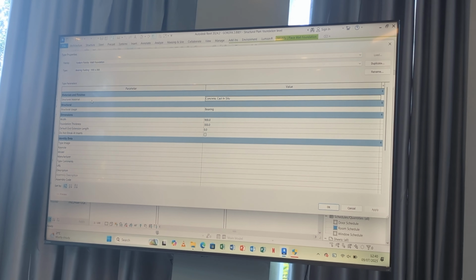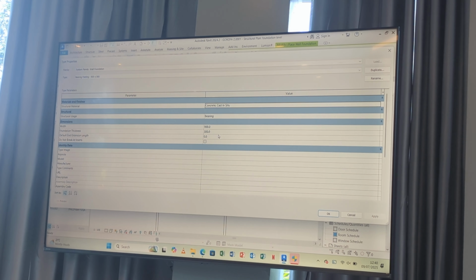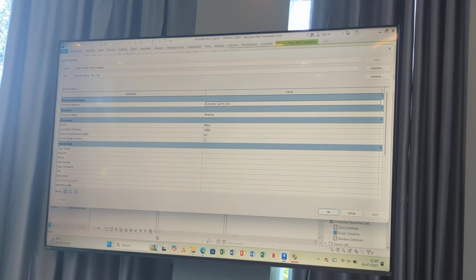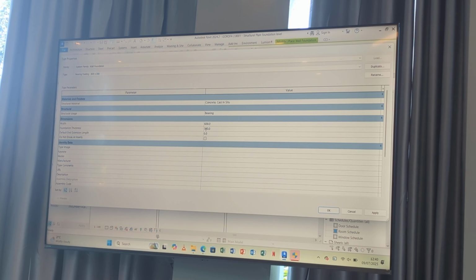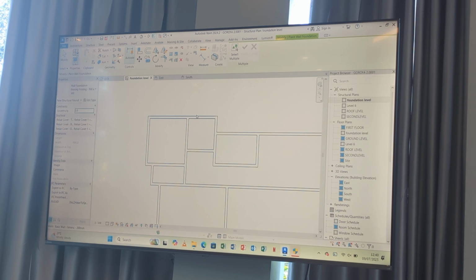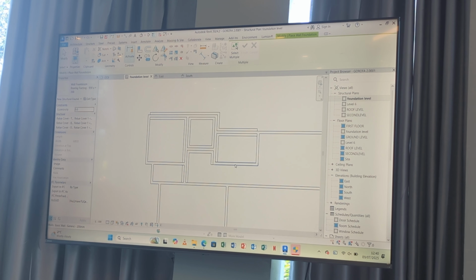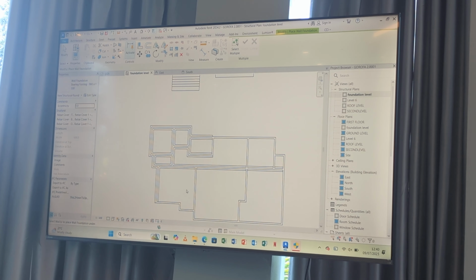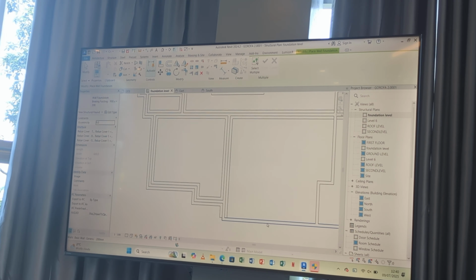But the thickness is also going to be determined by the type of site you have. Okay? Yes. So I want to change the width of this to 6 and the thickness of this to 2. Apply. Okay. So I just go clicking. See that? It's just creating that. So it's creating it at the bottom. Remember where I selected, it is creating a wall footing. So that's exactly where it's going.